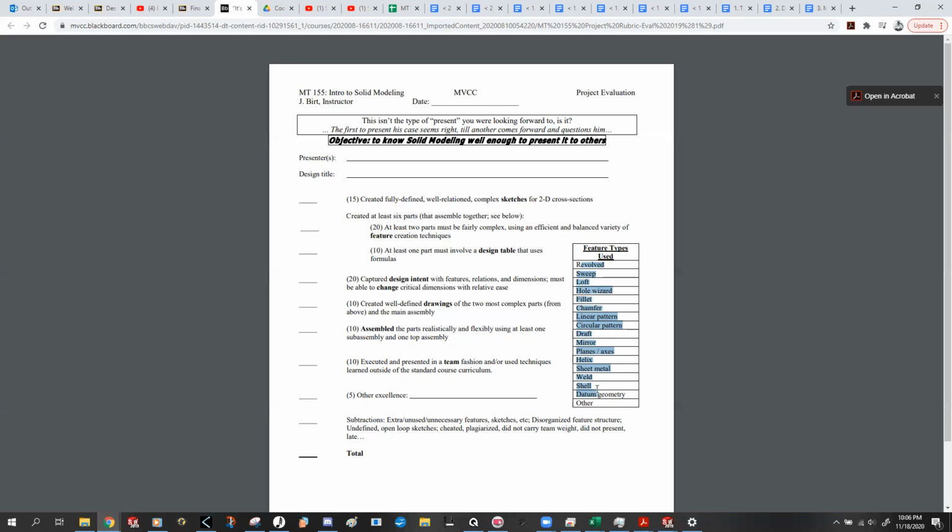You should use what you need, what makes sense. But you can use a loft to do some really cool things that just some of these won't work for. But maybe a revolve section will do the same thing, just differently. I don't know. But whatever you do, try to use a variety of these different things that can work. So if you've got something that has a pattern, then by all means, try to use a linear or circular pattern, whatever works for it, okay?